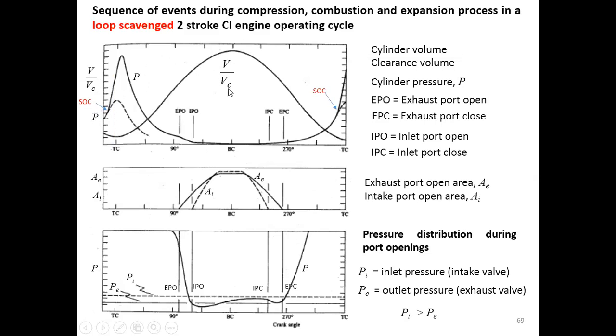So this first diagram shows you both the ratio of the volume, and also how the pressure is distributed along the way that the crank moves. Okay. So right here, the start of the combustion happens before the top dead center. So again, we know that the combustion happened because the pressure line deviates from the motoring curve here. So the pressure goes up and reaches the maximum.